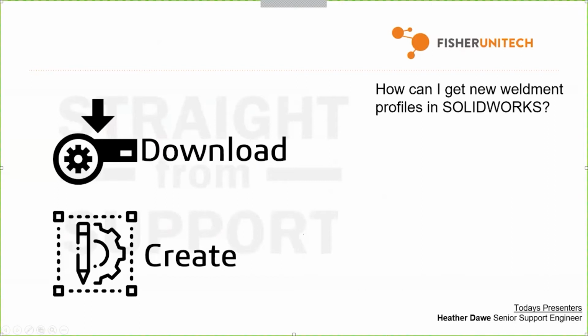And so that's how I can go and just really easily create Weldment profiles from within SOLIDWORKS without a whole lot of steps, and I can really add whatever I want to, so I shouldn't have to be using sweeps in situations where I want to create a Weldment.